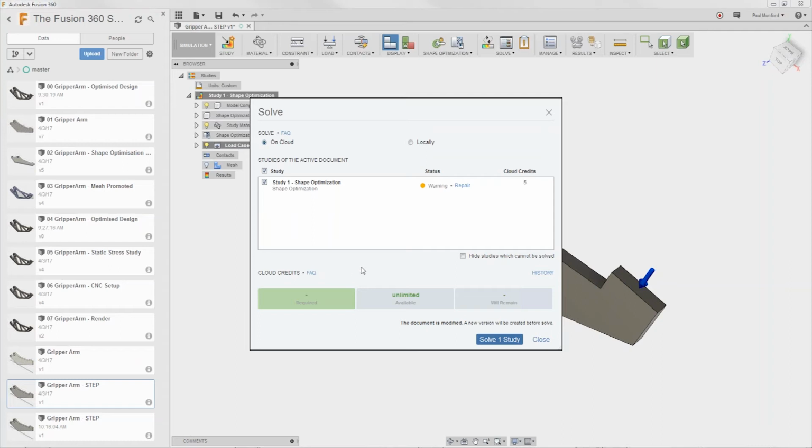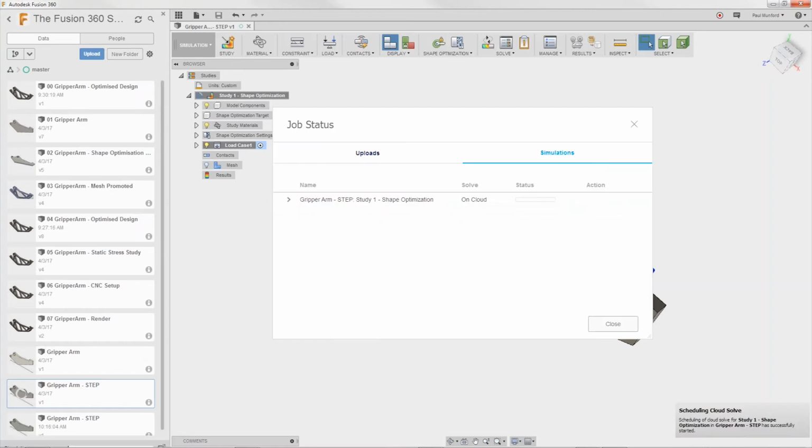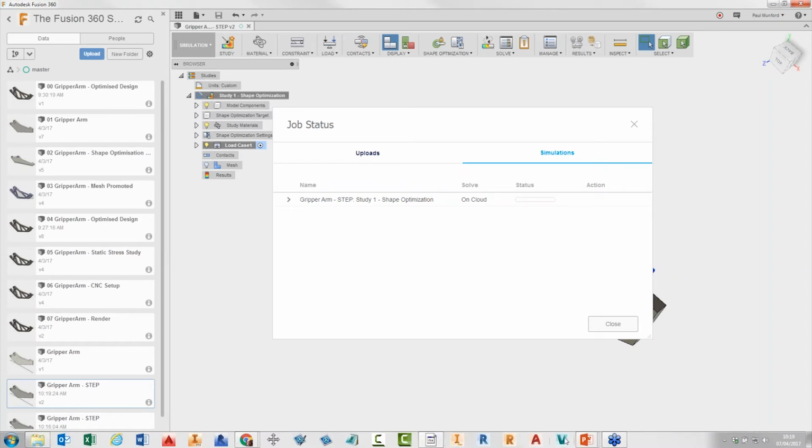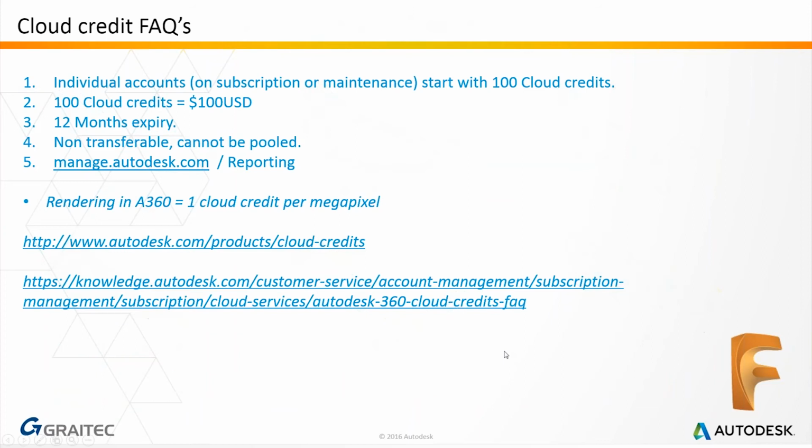So what I'm going to do is just add a preserve region here. And again, I've got everything appearing on the other screen. So I'll just add in a radius there of about 8 millimeters of material to be preserved. And then I will just repeat preserve region and set a preserve region on this little fella over here, and we'll make that about 6 millimeters of material.